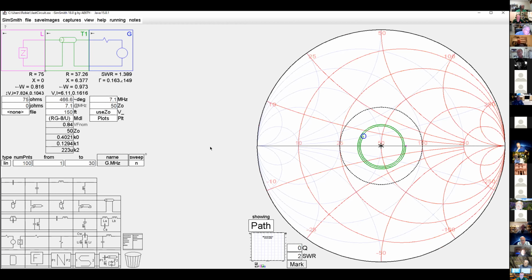Now, it's sometimes kind of hard to measure the standing wave ratio at the antenna, and it's sometimes hard to measure the impedance at the antenna, because the antenna impedance changes. So here's an example. Let's say I've got a small beam I want to put up, and I want to know what my SWR is, or what my impedance is. So I take my vector network analyzer that I learned how to use a few months ago, and I connect it to the antenna, but the antenna is only 10 feet off the ground, and I get my resistance value and my reactance value. That's all well and good, and I can compare that to a 50 ohm line and say my real SWR is going to be about X, but the antenna impedance is not going to be those values when it's 50 feet in the air. It's going to have another set of values.